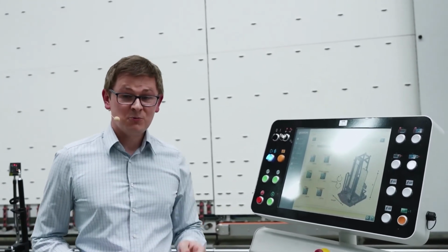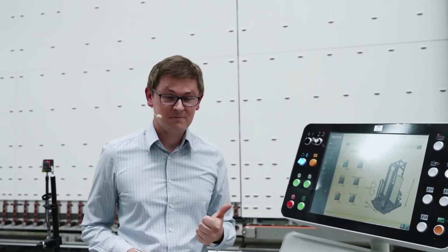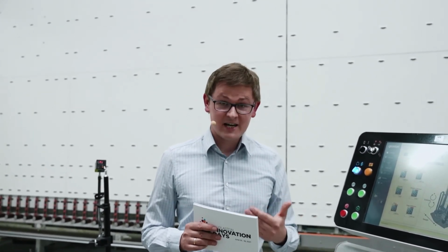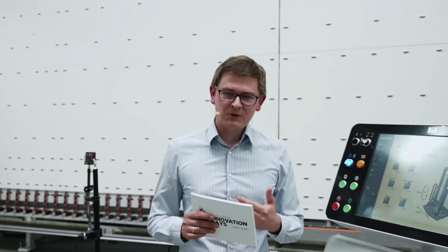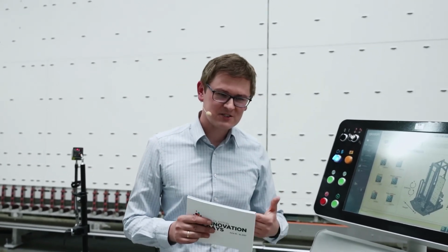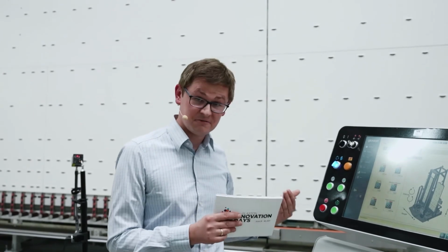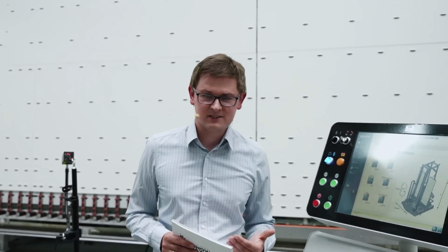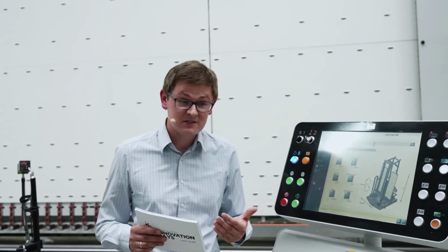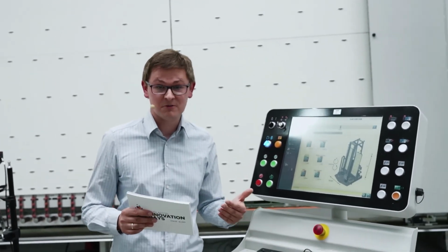The machine is able to work in two different basic ways. The first way is to use production data, which means that all glass parameters like size, thickness, and so on, are set in a data file, and the machine compares this data to the actual glass pane which is on the machine. If the operator takes a false one, which does not correspond to the settings in the file, there will be a message on the user interface and the machine will not process it. And it makes sense, because then maybe you block the complete IG line with a false glass.